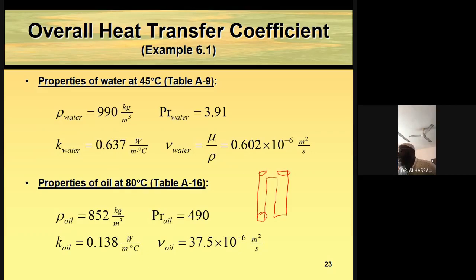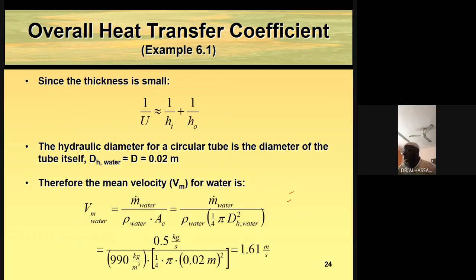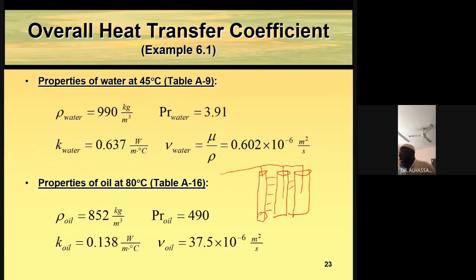And in between these flat tubes, we have fins. Fins are embedded in between the flat tubes, like this. So that the hot water, which is coming from the engine, flows into this. It is distributed into the flat tubes, like this. So as it flows down, the air will be coming with high velocity.